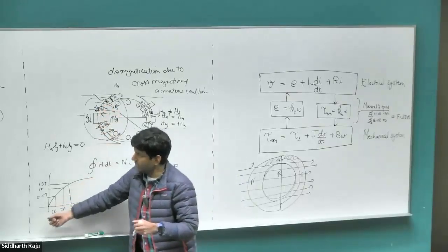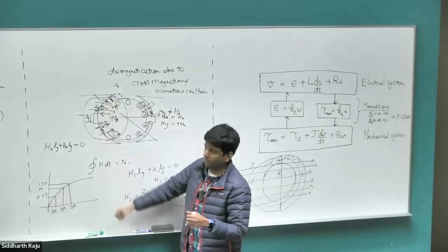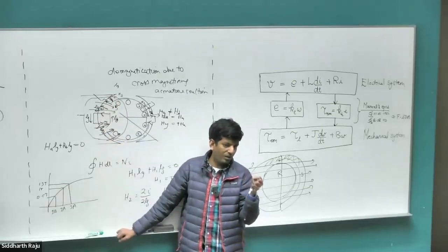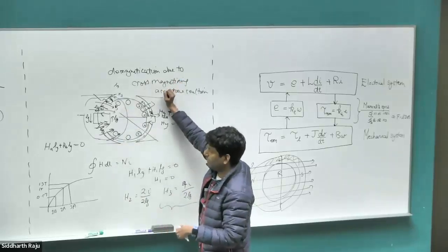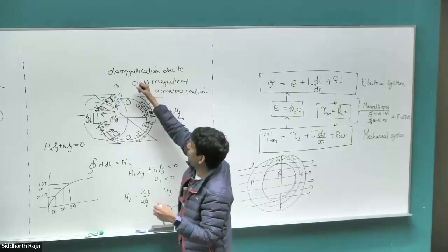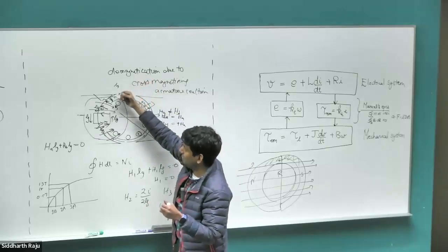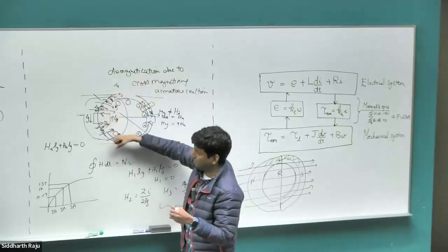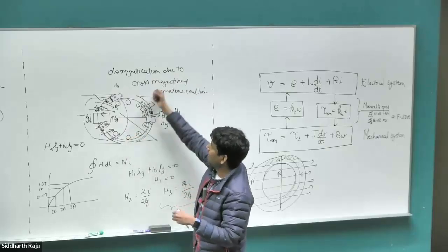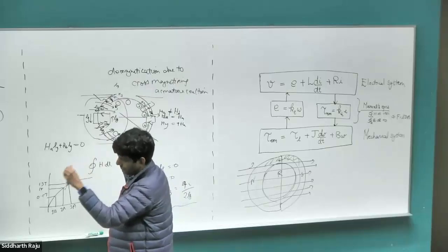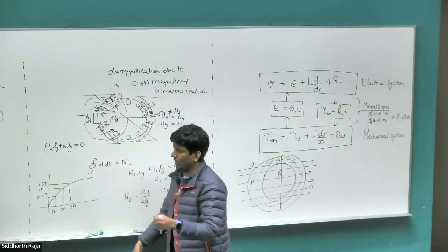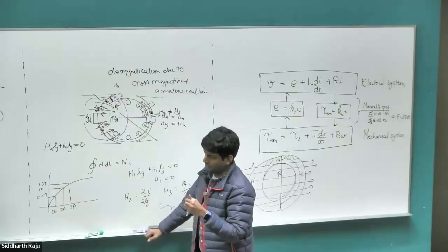So what that in effect is, over the total surface of the magnet, you have effectively reduced the magnetic field by a tiny amount of portion. Right? So that's why we call it the demagnetizing effect of the cross-magnetizing field. If it was a linear system, there would be no demagnetization in the net, because half the side is magnetized, half the side is demagnetized, so you don't gain anything much. But in reality, due to saturation, some portion of it loses more magnetic field compared to the other portion, which is gaining the magnetic field.